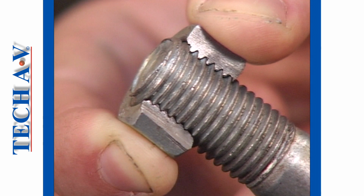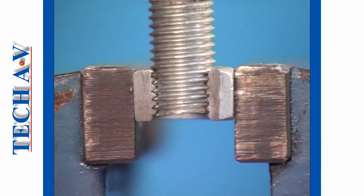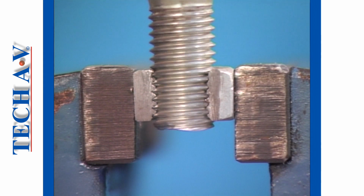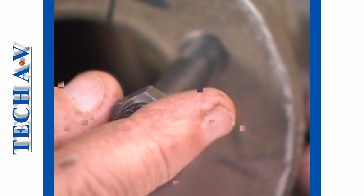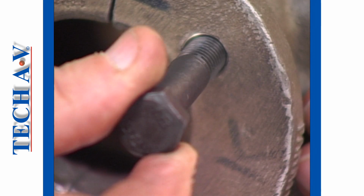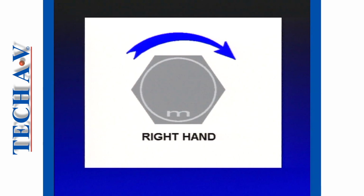The external thread is cut to the same form or shape as an internal thread so that they will mate or match each other. In this cutaway view, you can clearly see how the external and internal threads have engaged and how the threads travel along each other. Most threads are made in such a way that by turning a fastener in a right-hand direction, there is a tightening effect. We call this a right-hand thread.